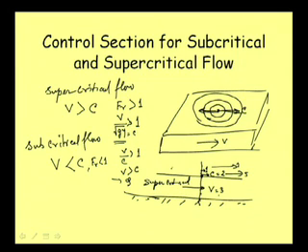Now for subcritical flow, if I draw this, it is coming like this and moving with a speed, say, 2. Then we create a disturbance here, which may be a wave or whatever, and it moves with a speed, say, 3. The celerity C is higher than the velocity V. So this is what I am drawing as V, and this as C.